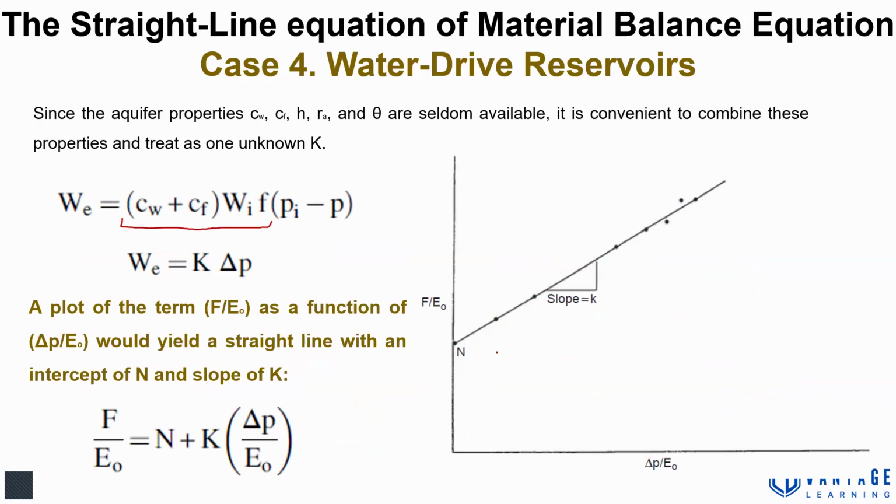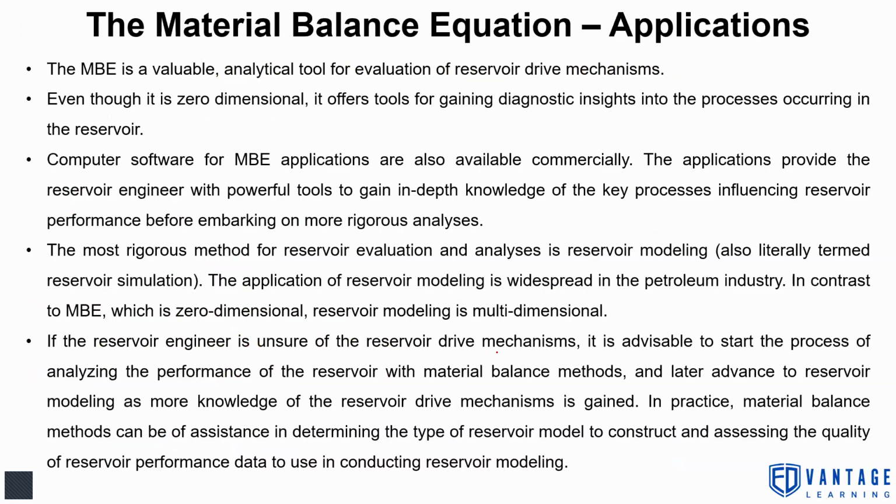So this is how we use the material balance equation as a good analytical technique to estimate in-place volumes, and also to estimate the gas cap volume that is available at the primary condition. We can also understand how much recovery factor is possible for this reservoir. So MB is a valuable analytical tool for evaluation of reservoir drive mechanisms. Even though it is zero dimensional, it offers tools for gaining diagnostic insights.